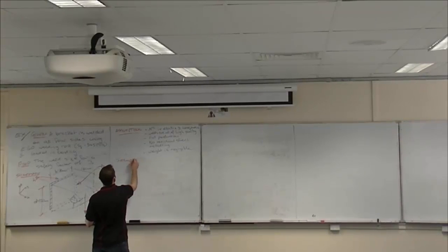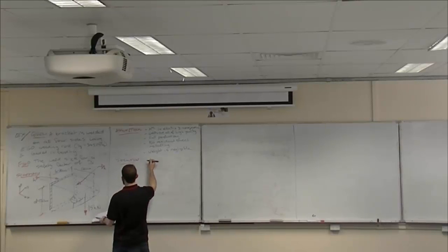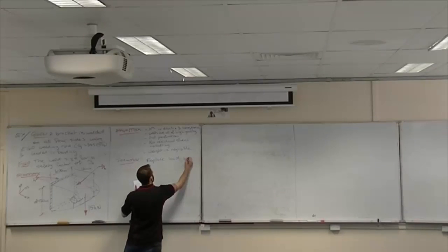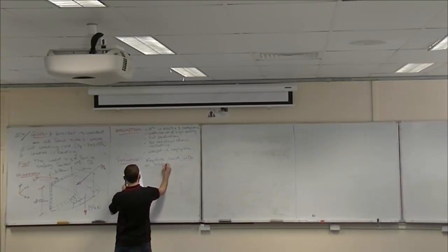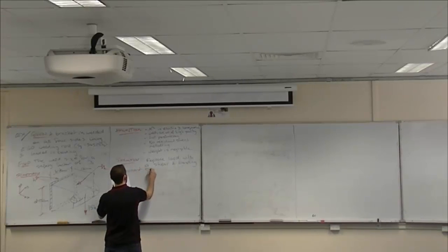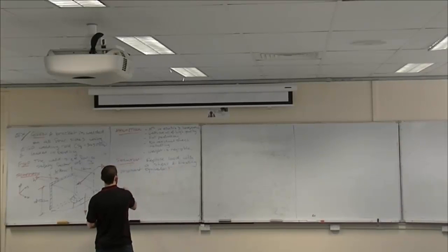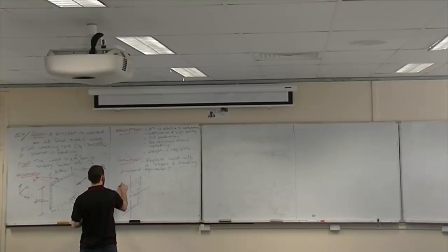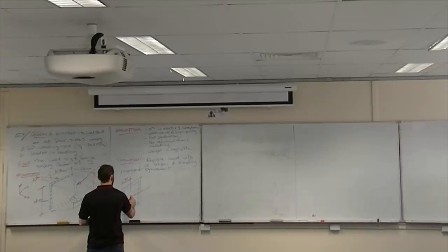All right, solution. So first of all, we're going to replace the loads with equivalents. Alright, and so I'm going to draw my weld group down here. And centroid, this distance are known to be half of those on the layout, 35 and 60. Then I've got an equivalent shear down at the centroid and equivalent bending moment that's sort of coming down the page.